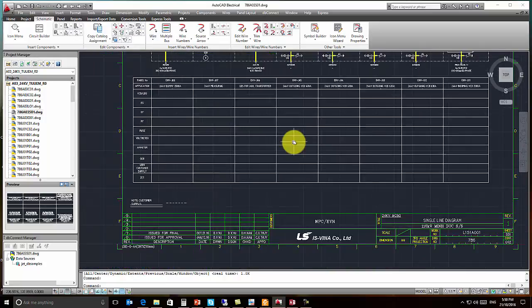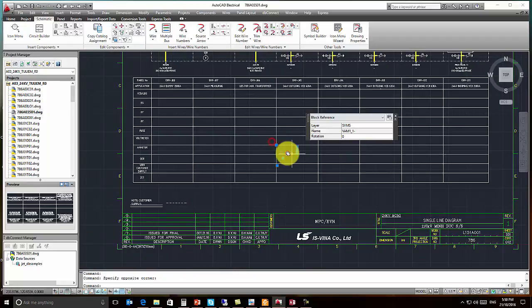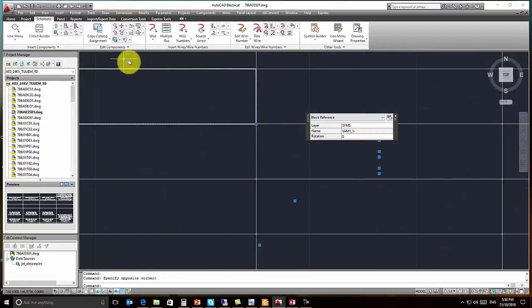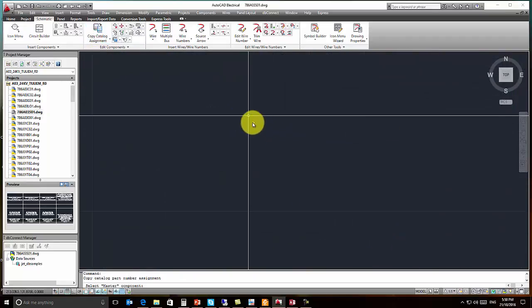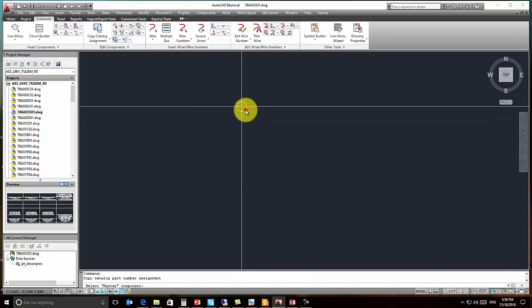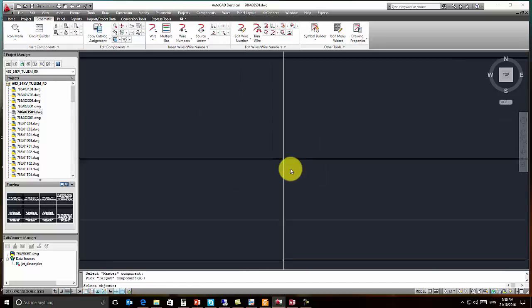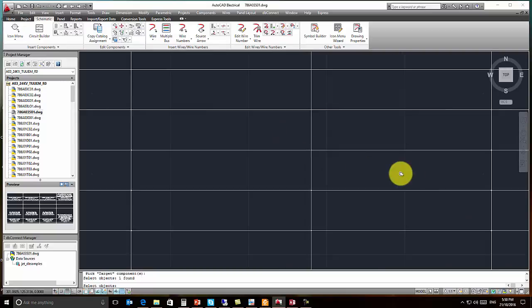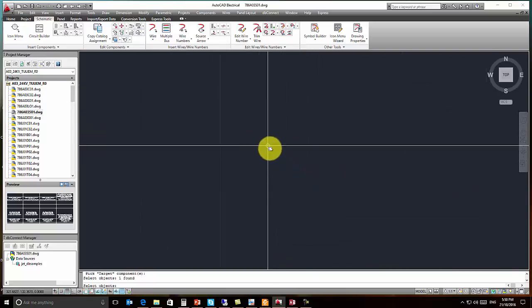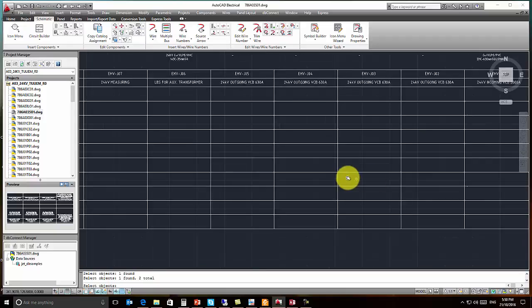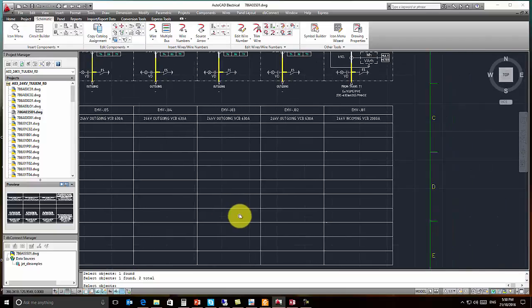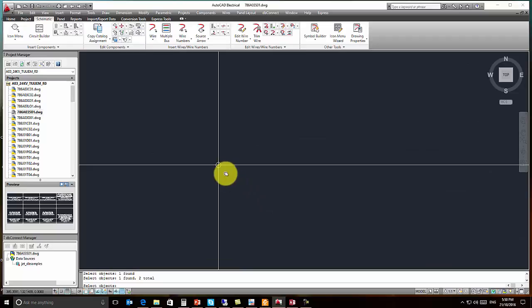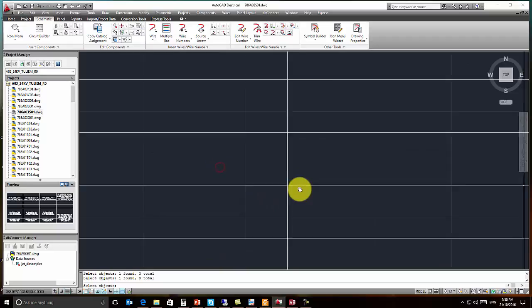Okay, so now we're going to block our attributes. We have all 15 of our attributes created here. We're going to block them, and we're going to block them in order. I'm going to go 1, 2, 3, 4. So you're going to see this go. I'm going to go block, and I'm going to go tag attributes. Tag X. Select objects. Now this is the important part.